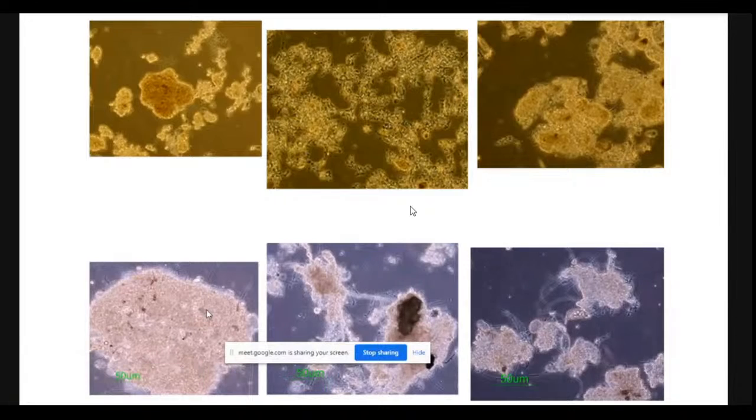All right. So if this kind of particles are there in the wastewater, then except the larger one, all will remain in suspension. All will remain in suspension. This will not get settled. So the idea here is that by injecting air at a high pressure, it not only passes oxygen, but also will try to break down this chain into smaller particles. Once they are smaller particles, the aeration will support them, and if you use the methodology called coagulation, then all these shredded particles will come in contact with the positive and negative charges, and they'll form bigger particles. And then some of them will settle down at the bottom of the tank, which can be removed very easily.